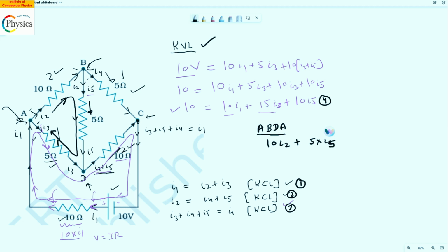Now, if you see this, the loop is the clockwise loop, right? So this particular arm is what I'm referring to. The current in this arm AD. So if you see the arm AD, the current is like this. So this is your current AD. And loop is in this direction, right? So loop and current are reverse of each other. So we will not apply a positive sign but a negative sign.